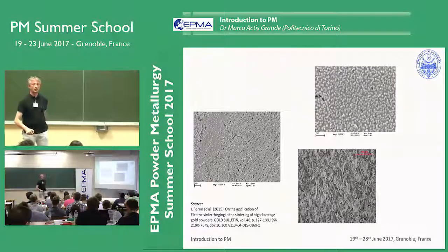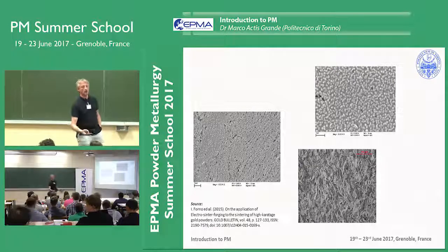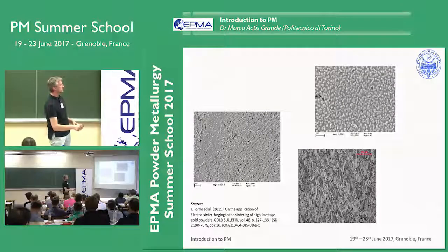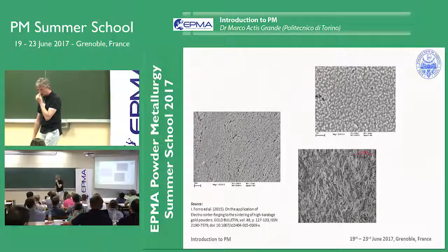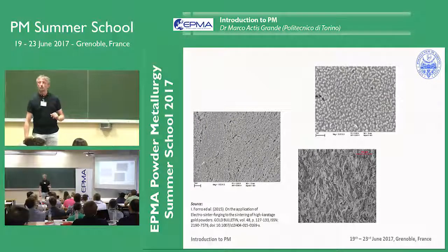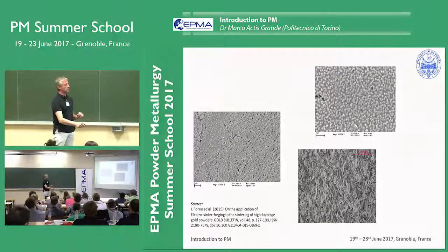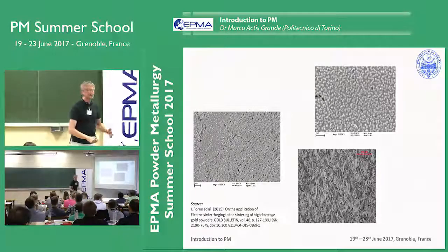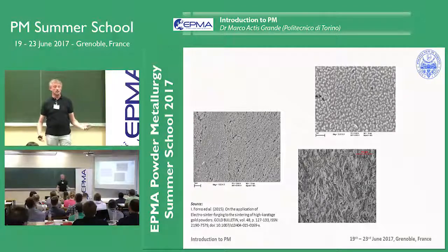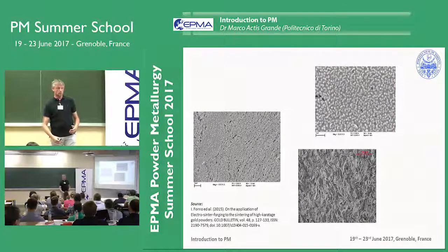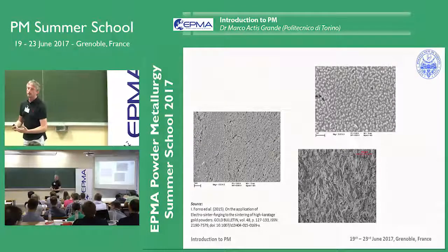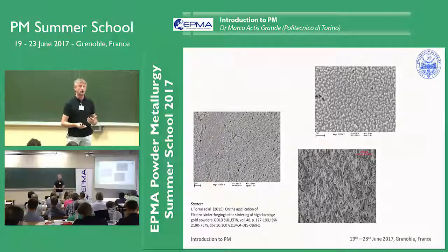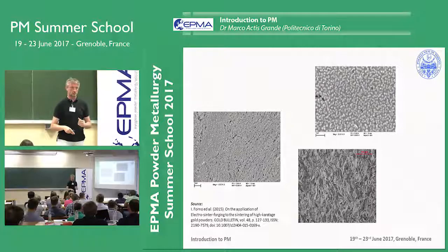But what is the best use for that? Due to the very short process cycle time, you can mix up components. Here you see, for example, a combination of precious alloys and gold and diamonds, which are treated together in order to get very hard precious metals. This is something that I will come back to later as for application. That's to say, this technique allows the combination of very, very different materials altogether, and the processing times are so short that it is not an issue to apply all the considerations that are to be applied when a thermal process is used.